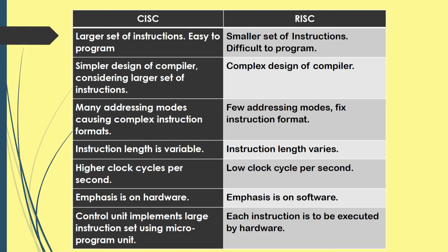In case of CISC architecture, typically complex instruction set decoding logic is used. It is driven by the need for a single instruction to support multiple addressing modes, a small number of general purpose registers, and several special purpose registers. Many CISC designs set aside special registers for the stack pointer, interrupt handling, and so on. So this can simplify hardware design somewhat at the expense of making the instruction set more and more complicated.